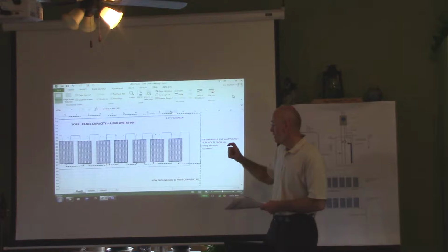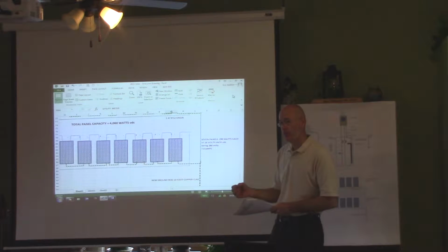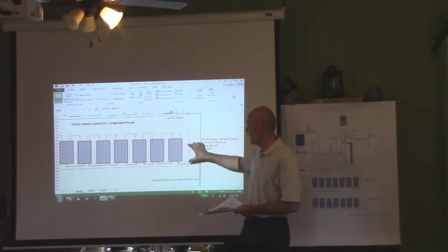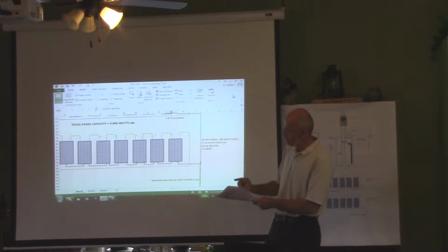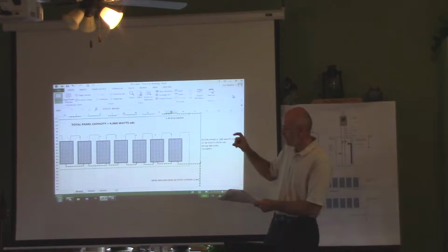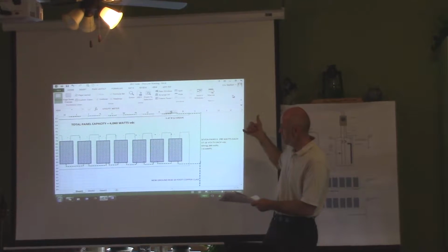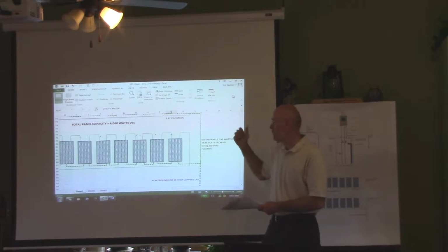I'm getting lots of different images for you so you can all get it. Flashlights have multiple batteries in them. Each of them is about 1.5 volts. You stack up your batteries, and each time you add a battery, you're adding the voltage in series. So if we have a 6 volt light bulb, we need to get to 6 volts, so we put 4 batteries in there, each 1.5 volts. That gives you 6 volts. Now you have the right voltage to drive the flashlight.